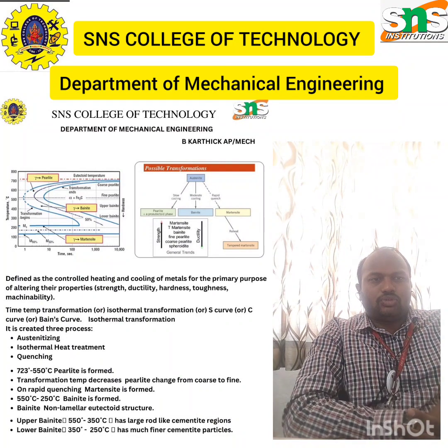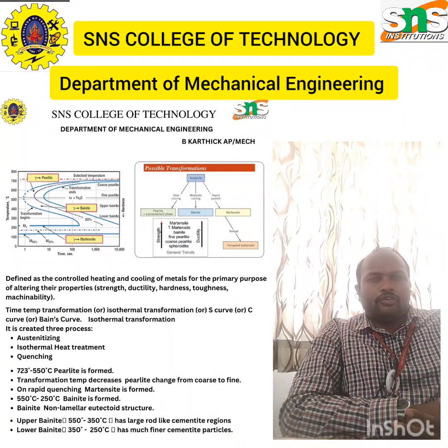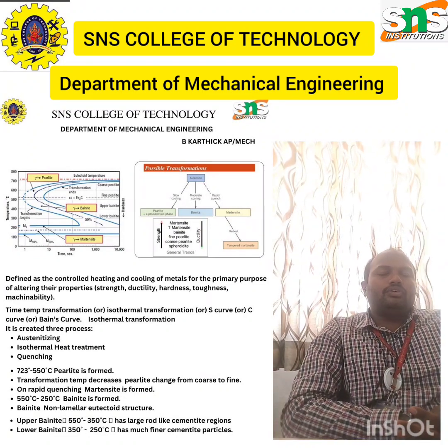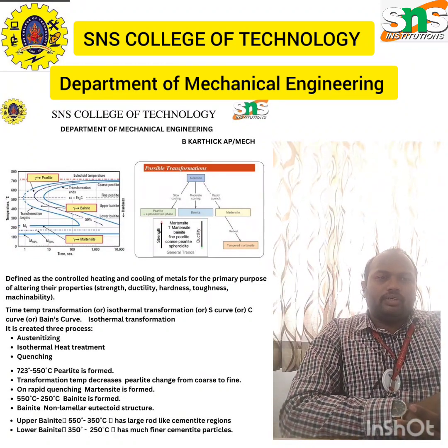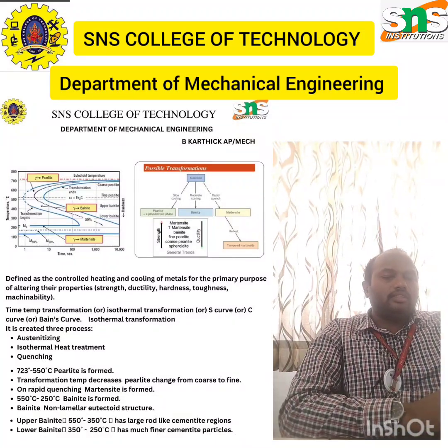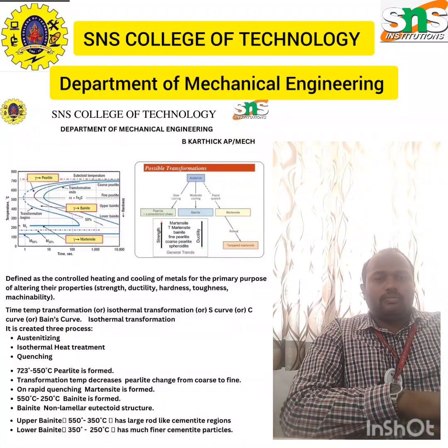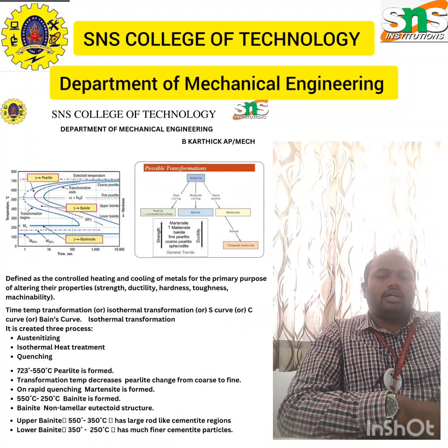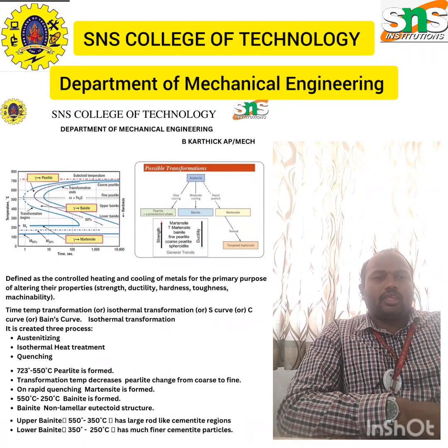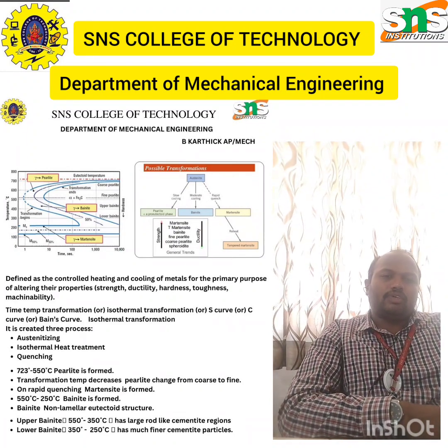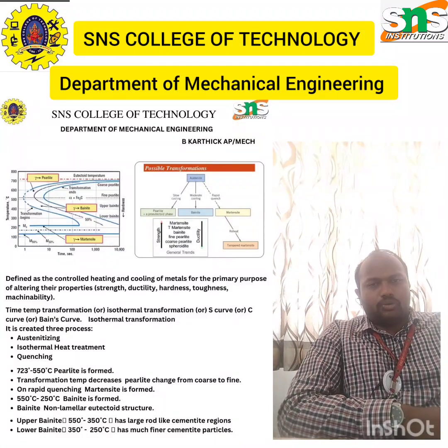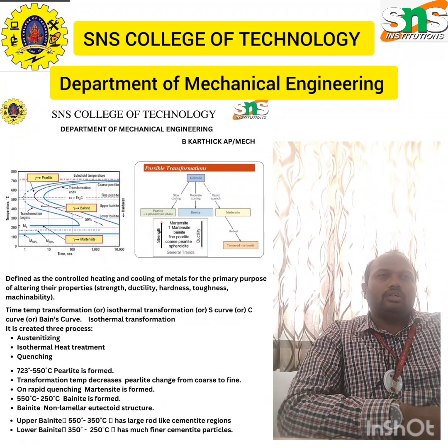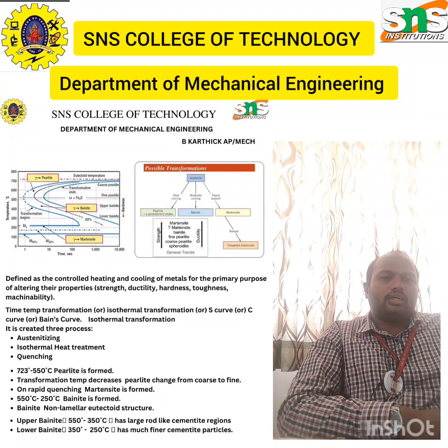Speaking about hardness, the first factor is the carbon content. If you want to increase the hardness of a material, we have to increase the carbon content of the metal. Increasing the carbon percentage will increase the hardness of the material. The second is that if you cool the material much faster, the hardness will improve. As I said about the PVC pipe previously, upon faster cooling, hardness will improve.